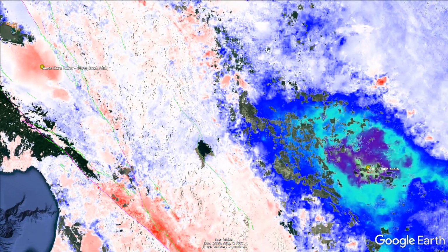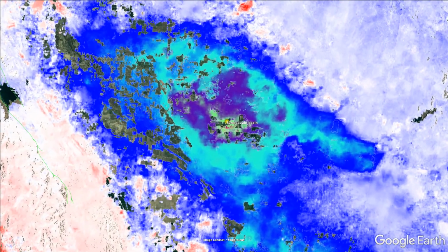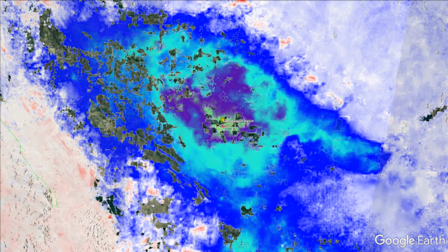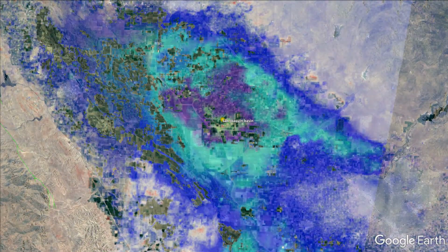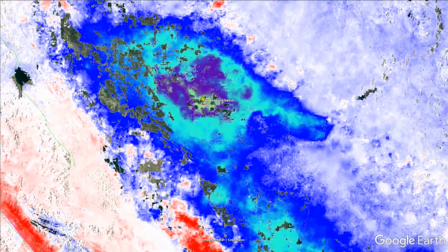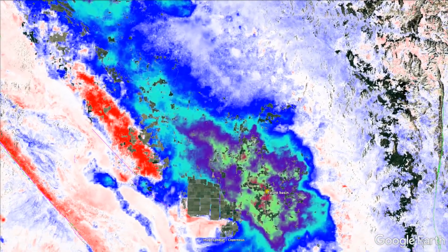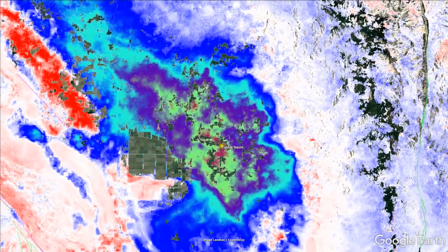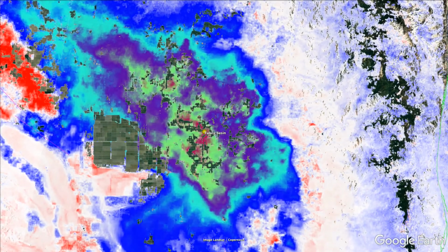Moving to the southeast, into the Central Valley, the San Joaquin Basin is subsiding rapidly. Using the transparency, it is evident that this subsidence is related to rapid water extraction, especially during the California drought. Moving further south, near Tulare, the ground subsidence is more rapid, with the largest rate over 400 mm per year.